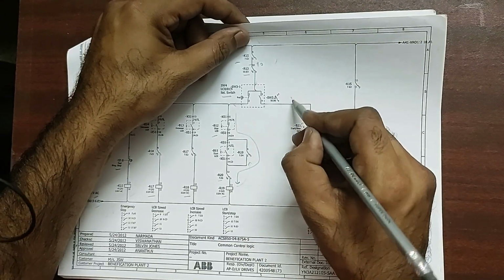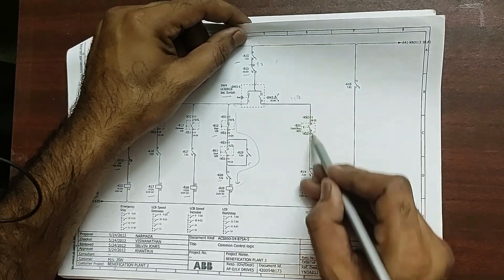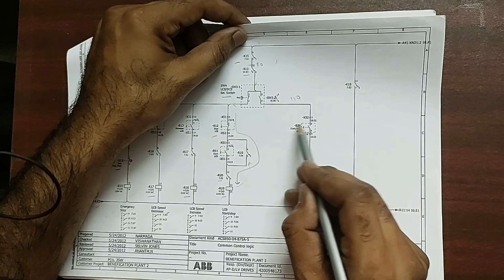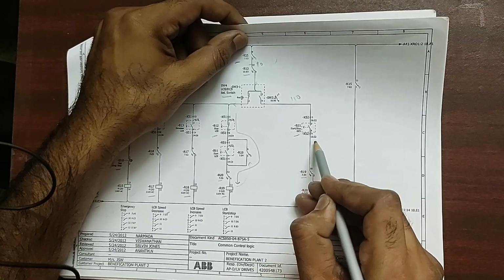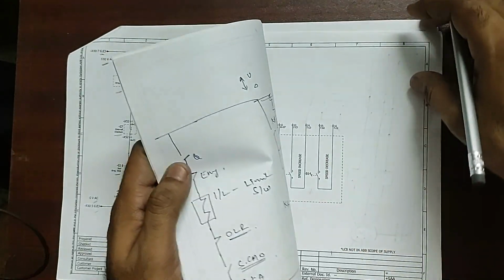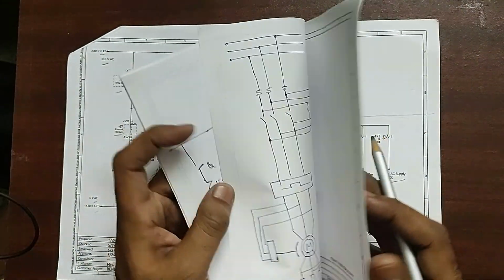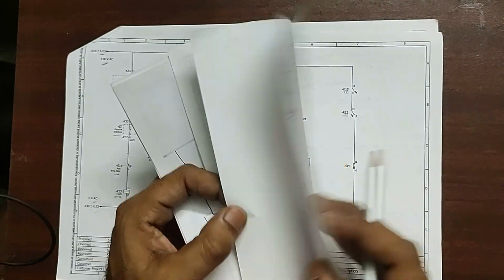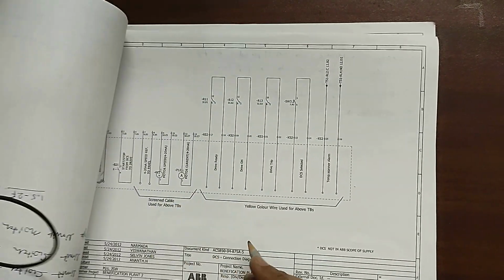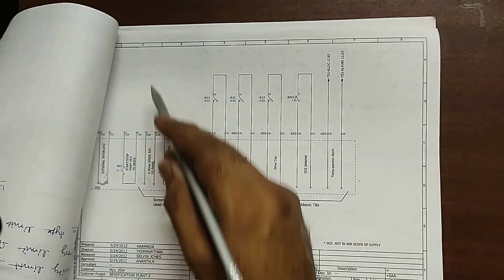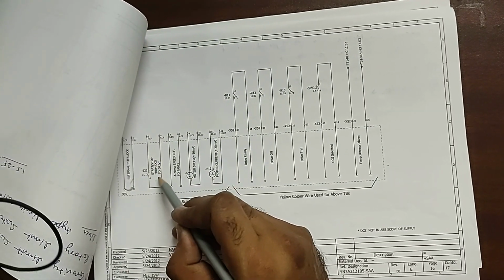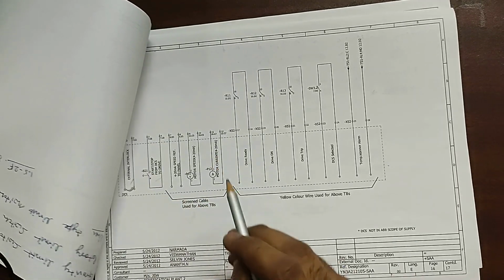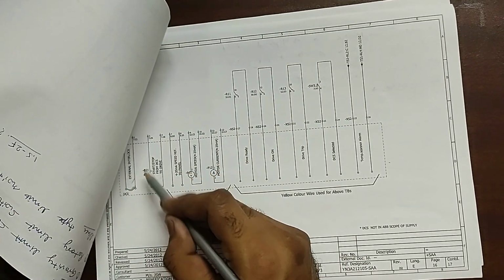We'll come to the DCS part. So 110 volt will come here, and this is the command coming from the control room. Start stop from DCS, 16C2. You can cross check it. 16D and 2C. Start stop from DCS to drive. This will give a command that you can see in the RIO panel.